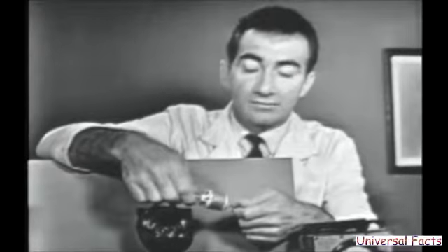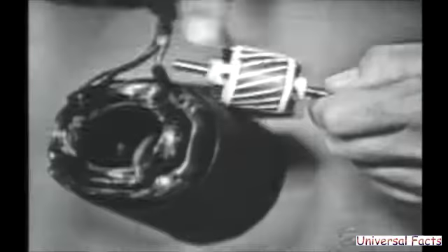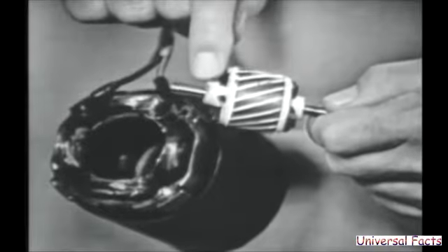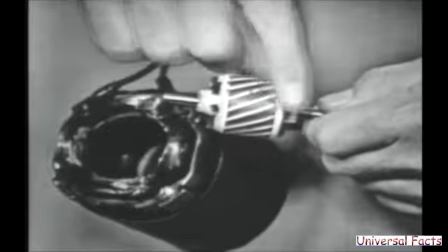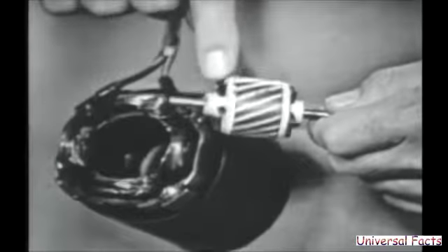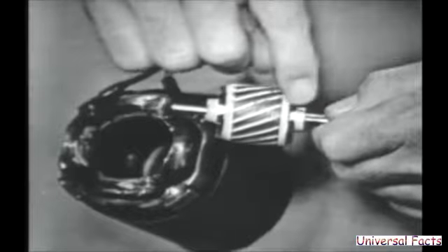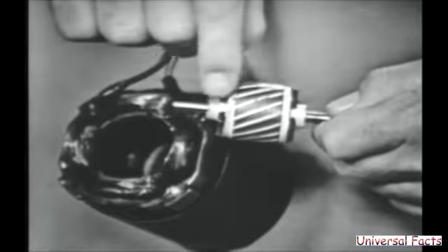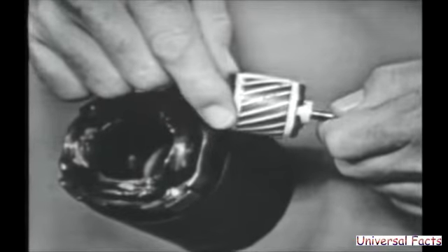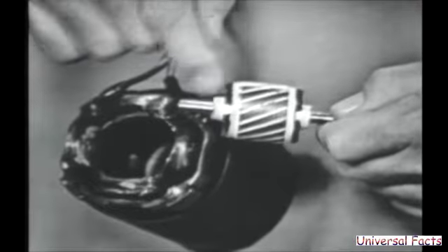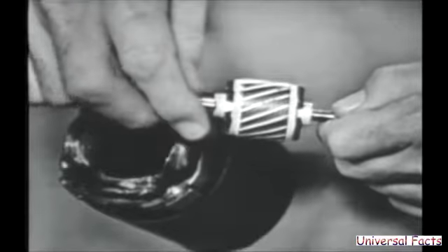Now, actually, the rotor is almost the same thing, and a rotor is made in a very similar way. Instead of using windings of wire, however, we use a conducting ring on this end, a conducting ring on this end, and they're joined together by conducting bars, these little white lines. Sometimes they're made of copper, sometimes aluminum. This one happens to be aluminum.